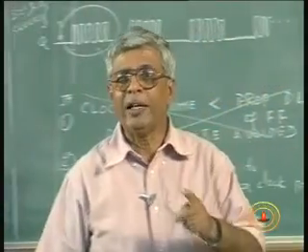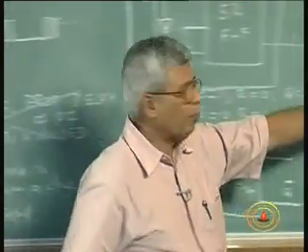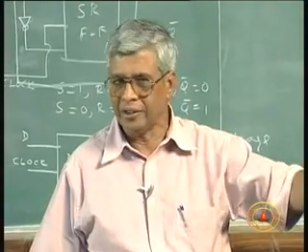In that case, I have one extra feature of my SR flip-flop. The SR flip-flop will work as it is. There is no problem other than the 1-1 condition. It's a good flip-flop. Don't think it's a bad flip-flop. With clock 0, it behaves as a memory. With 0-0, it behaves like a memory. With 0-1, it is reset. With 1-0, it sets. These three features are common.